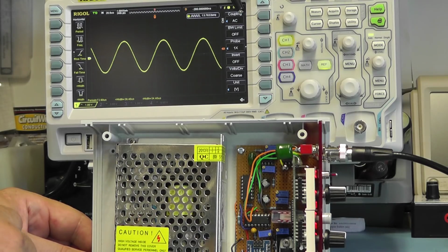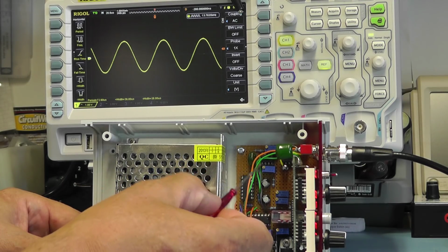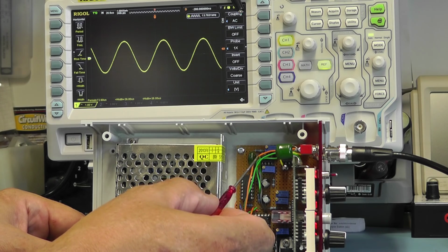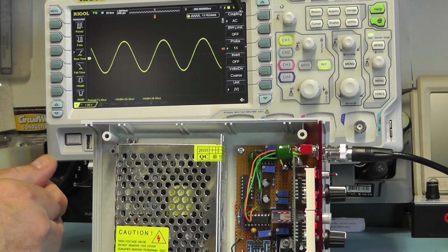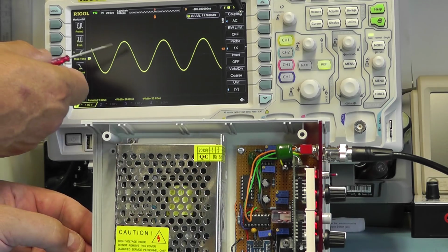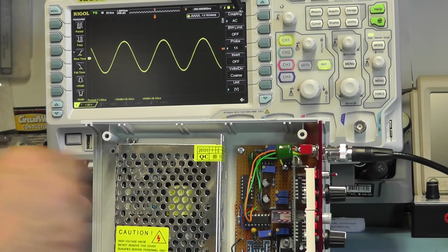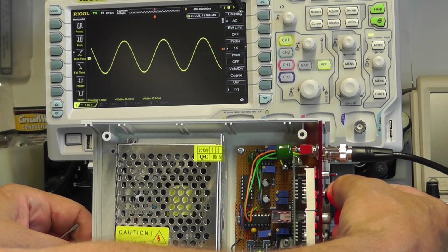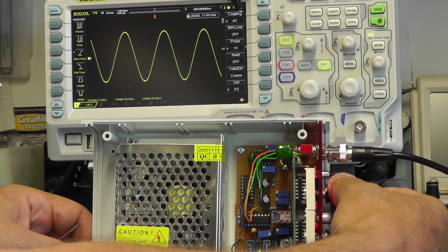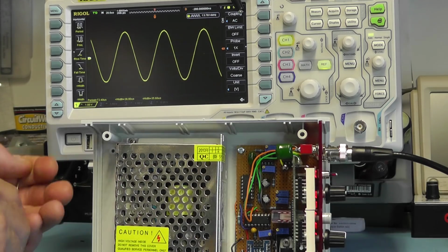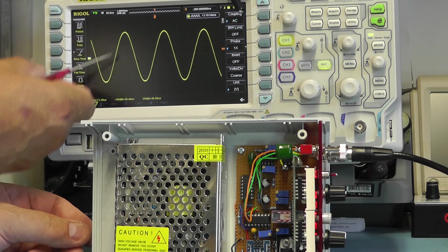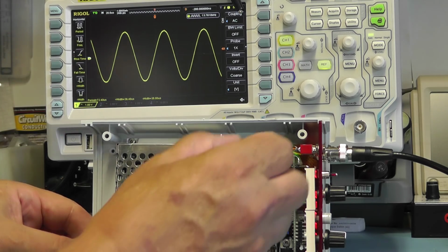I'll just quickly show you how to set these two presets here, which are in the output stage of the op amps. Basically what you do, quite simply, set the function generator initially for a sine wave output, turn the gain control potentiometer fully clockwise for maximum output, and note the reading. And what we're looking for here is a reading of around 6 volts peak to peak.